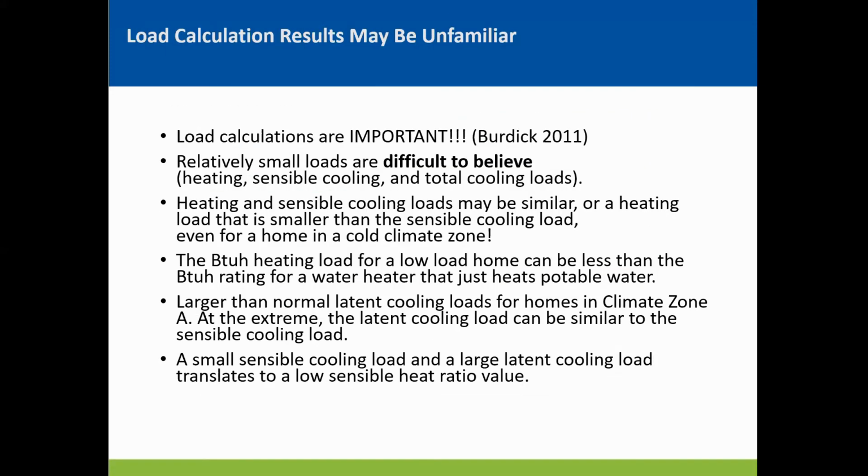We talked about the loads being very important. Well, that's actually the problem with a low load home, that the loads are so low that contractors and designers don't believe that they're that low. The heating and the sensible cooling loads are likely to be very similar, even in a cold climate zone.